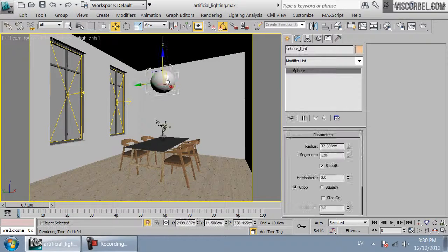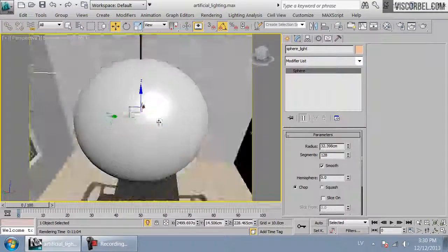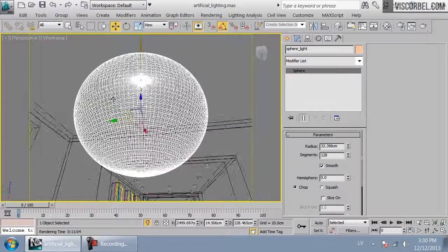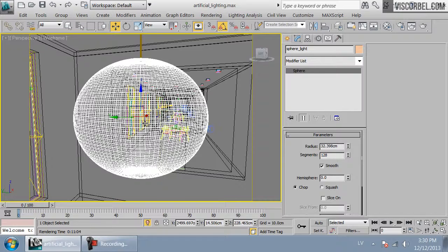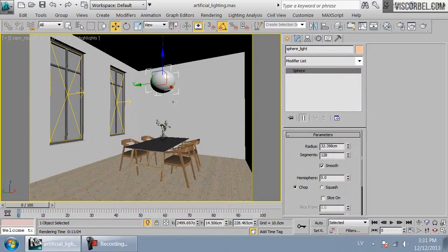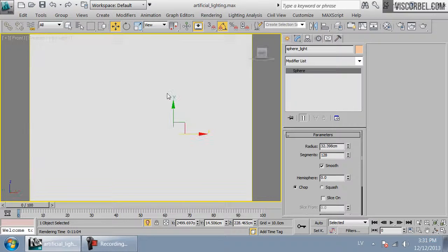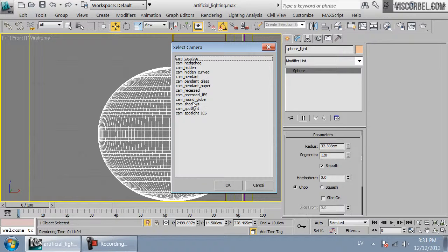Okay, so here's the scene, and the lamp here is a huge round sphere. So basically you would have a light source inside, and the light would get slightly dimmed by the sphere and diffused throughout the whole room. So if you would render it using the same technique I just did for those pendant lamps, it could be quite long and quite noisy, so you can use a simple fake to simulate this effect. So in this case I recommend creating a new material.